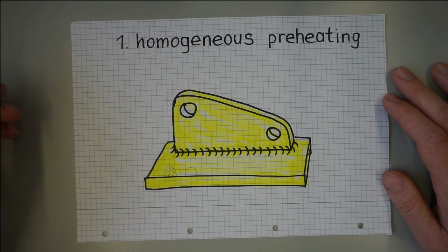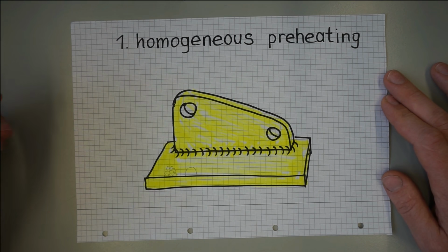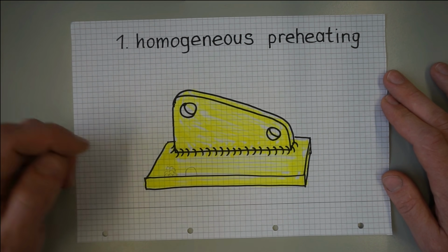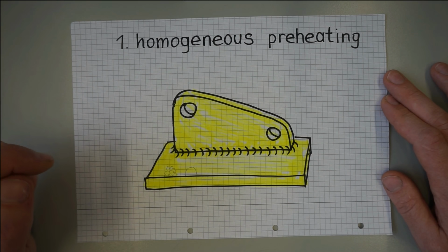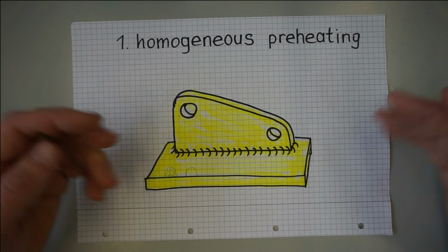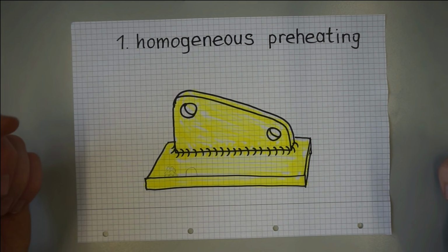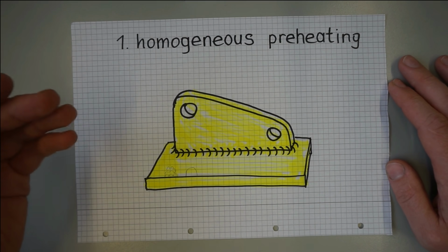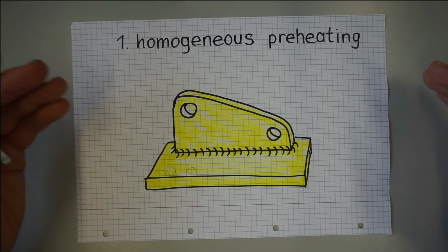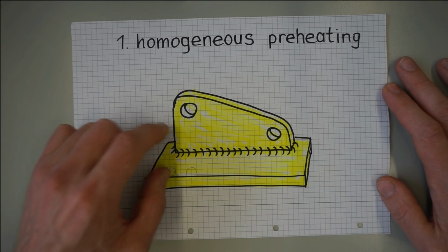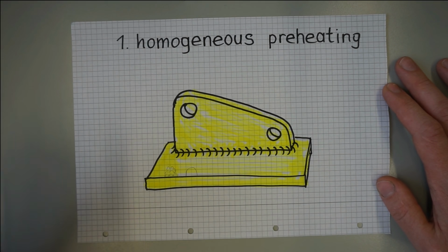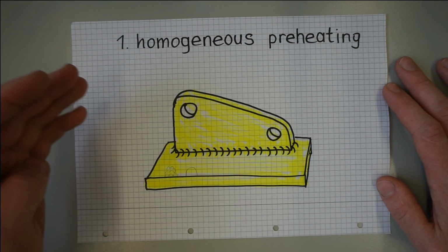Aside from that, allowable preheating temperatures can be limited even more by other processes, like, for example, carbide precipitation, which embrittles many stainless steel alloys. In other cases, homogeneous preheating can be impractical because of workpiece size. Just think of a ship's hull, for example. Or because it's unreasonable for the welder. Think of a workpiece inside of which you have to be for welding. For example, a boiler, a crane chassis, or what have you. So even though preheating may be the most effective strategy to reduce solid body distortion, there are well-defined limits to its application.